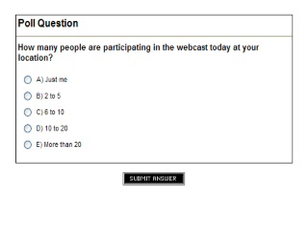If I understand you correctly, that means when I have a small footprint, my option is to put in more chlorine before you discharge it, and do more dechlorination, so that you meet the limit of the residual chlorine.